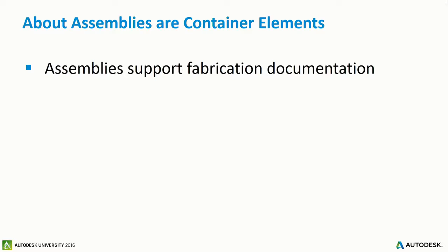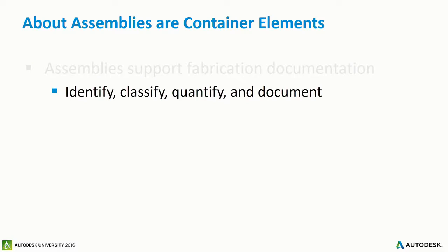So an assembly in Revit is a container. It's a logical grouping of elements. It's not a thing. It's not an element. It doesn't consist of physical geometry. It's an idea that wraps up a set of elements. So we have elements that are members of an assembly or not members of an assembly. Okay? And that assembly membership defines whether they're included or not.